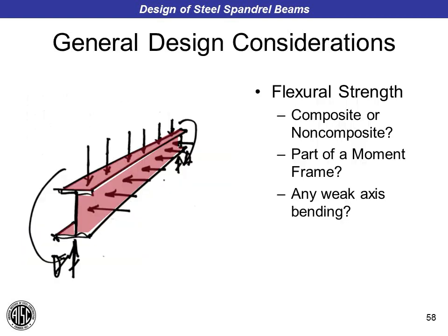Some things that go into this are whether the spandrel beam is composite or non-composite, whether it's part of a moment frame, which might restrain vertical displacement and also restrain torsion and torsional warping at the ends of the spandrel beam, and whether there's any weak axis bending on the spandrel beam due to out-of-plane loads from the facade.